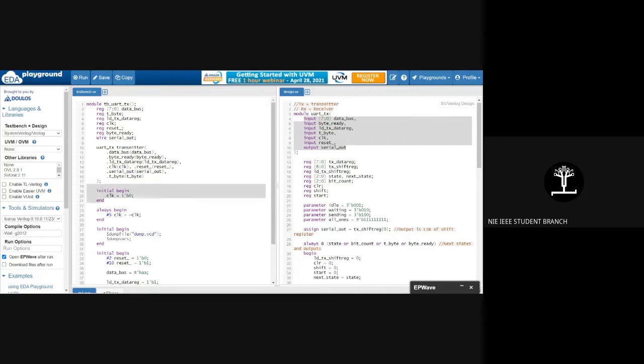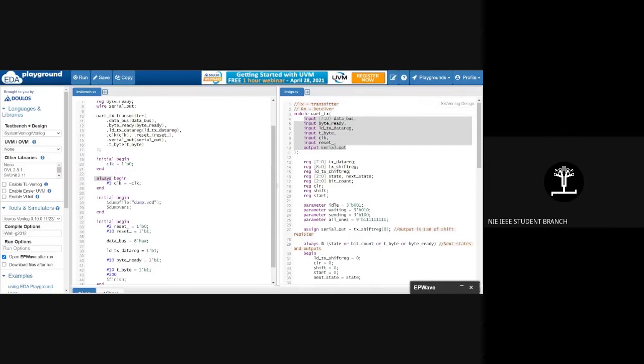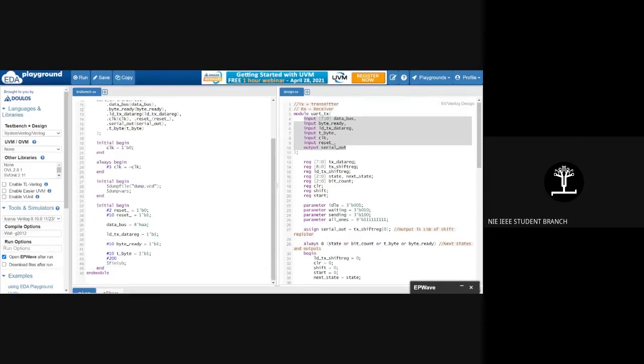So this is our normal thing. I begin with the clock signal being 0, and after every 5 time units I tell the clock to be the complement of the clock. That's in an always block that happens until it encounters a $finish, and then the dump file, as I already told you what that does.